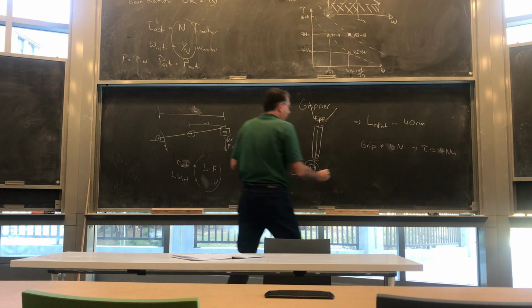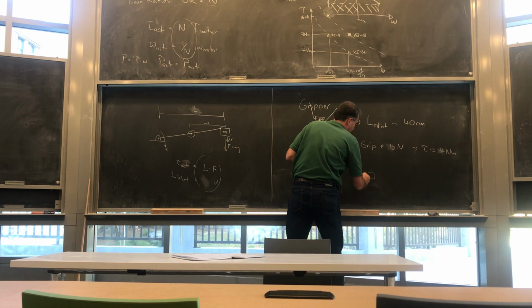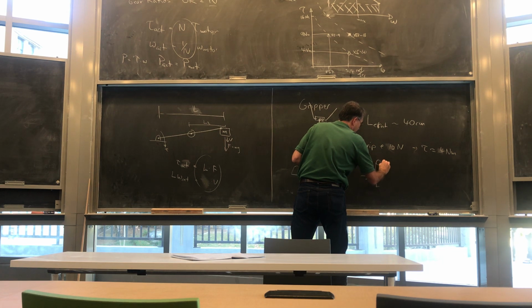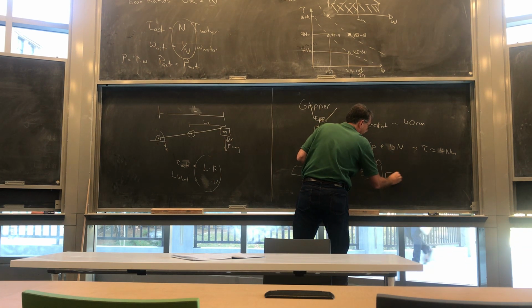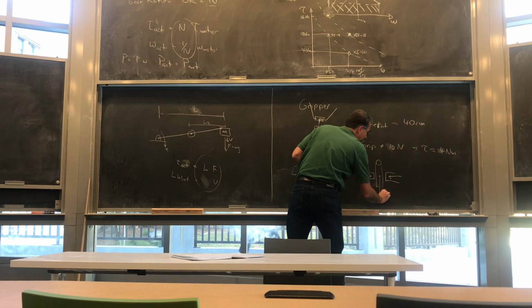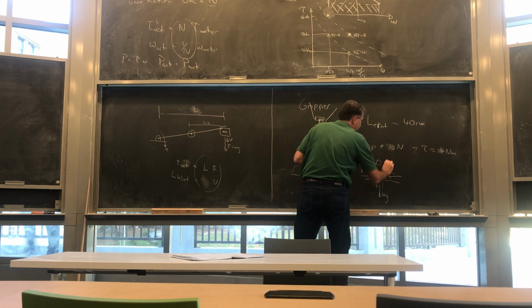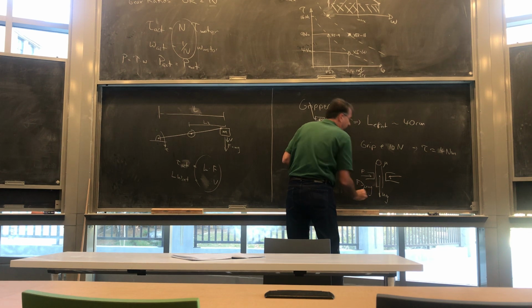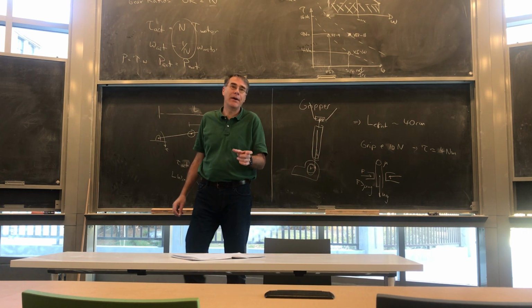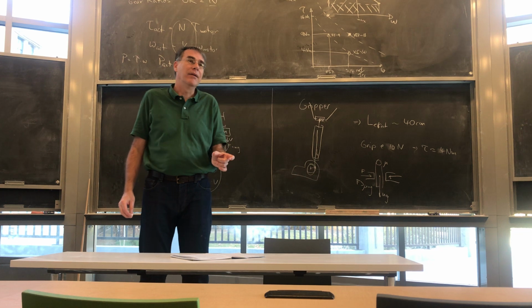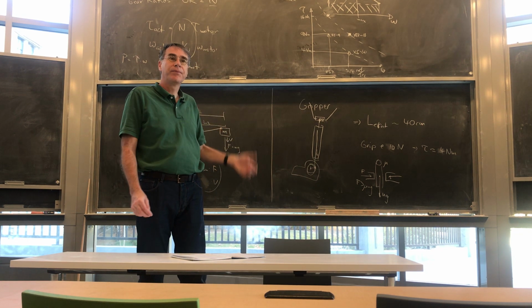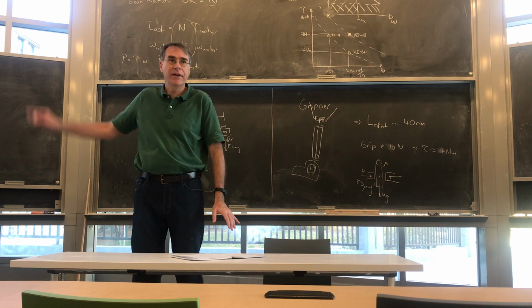Think about your fingers squeezing on an object. You can stick anything in there that you want. If there is an mg in the object, and there's a coefficient of friction, then obviously F has to be greater than what's needed to hold that. How heavy an object are you going to want to pick up? 10 newtons seems like it's plenty strong to me. Does that make sense? Is it getting boring?